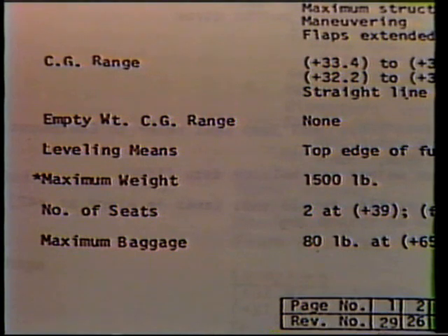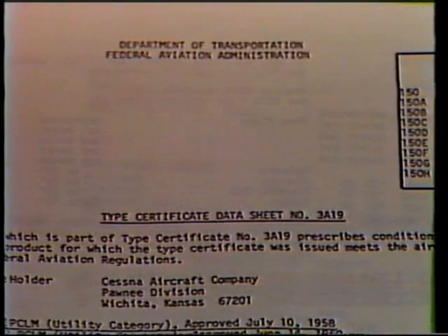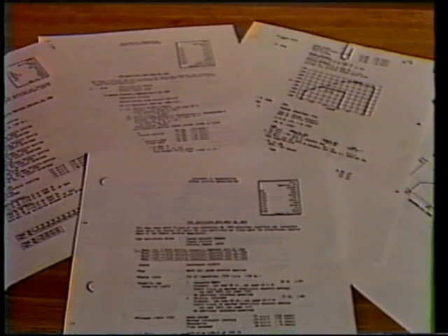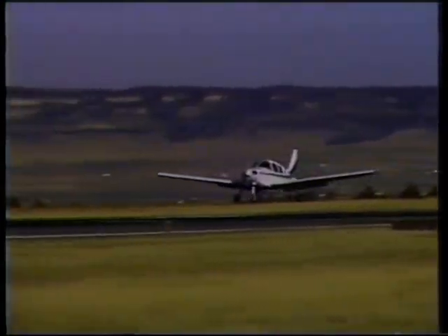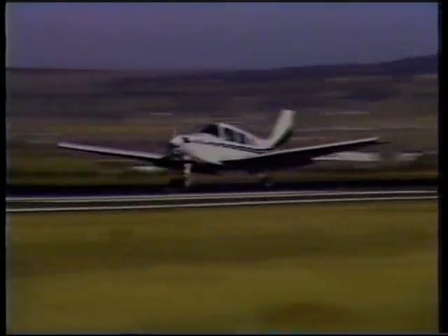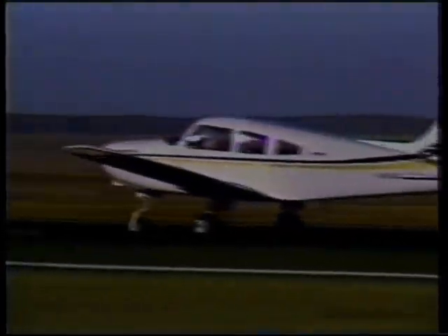Aircraft are designed to carry a maximum amount of weight. This maximum, or gross weight limit, may be found in the aircraft type certificate data sheets, aircraft specifications, or aircraft listings. These are Federal Aviation Administration documents, one of which is issued for every aircraft certified in the United States. Overloading the aircraft beyond the gross weight limitations may place dangerous stresses on the structure, especially in rough air or during a hard landing.